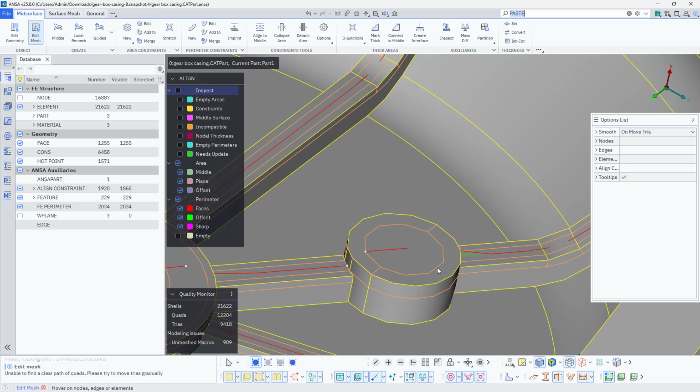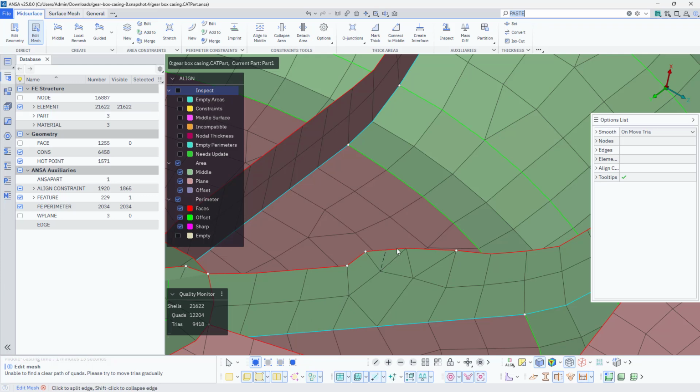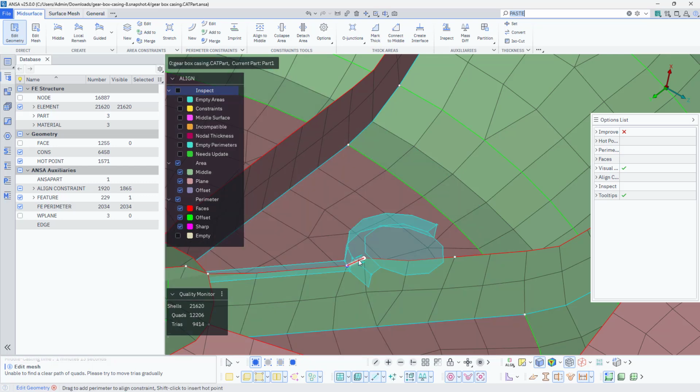As we had a kind of slot mount region, it is missing now. So what do we do with this? To deal with this region, you can activate the geometry again, press Q, then select this edge and drag and drop it to the adjacent edge, which is completely flat, and the tool will help you maintain the same. You can even directly remove these points.